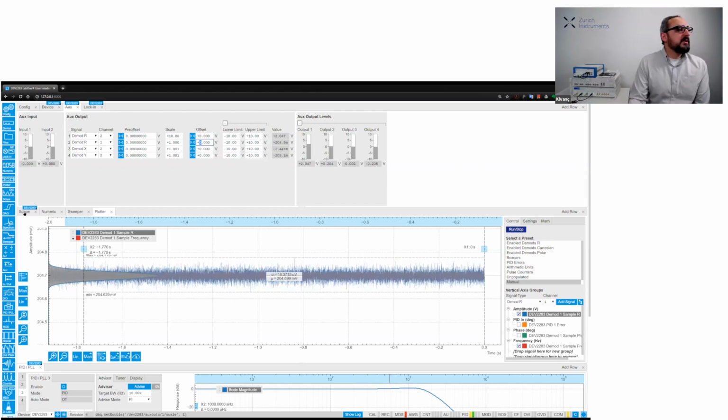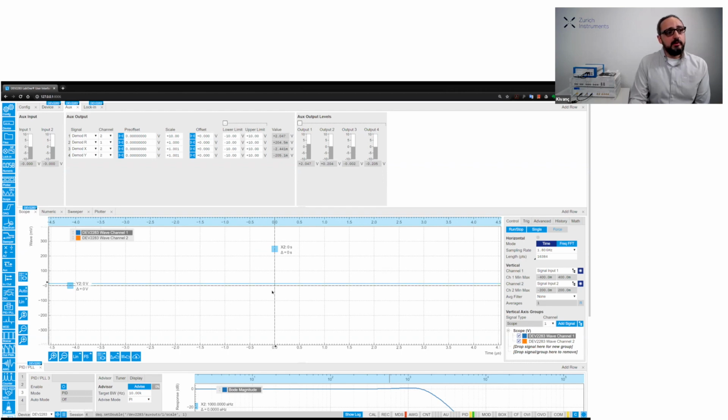Yes, so that's what I was doing actually in a bit. We have the scope, of course, and with the UHF-LI, you can even measure up to 128 megasamples per second as two channels. And any signal you will get, of course, then you will measure. But one important aspect, if you are talking about arbitrary waveforms, is to have the triggers so we can align the scope shots with the incoming arbitrary waveform. And for that, we also have several trigger channels. In the front panel, we have 2, for example. Also, we have digital input-output channels that allow you to first read other outside signals and also align the measurement with it using all the trigger and digital channels.